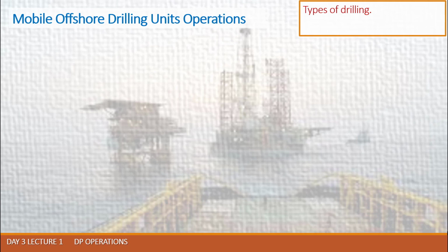Riser is a pipe which separates the drilling pipe from natural water environments. And that riser is a subject of tension, and that riser is a subject for accidents and incidents in the offshore industry, because riser is always under tension, and this tension must be monitored. And if tension is lost in the riser and it is no longer totally supported from the rig, the riser will sag and some of the weight will transfer to the stack.